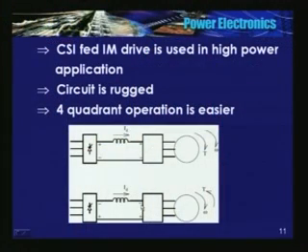Now we want to go to the second quadrant or fourth, depends on which one you have taken, T along x axis or y axis, it does not matter. So what do I need to do? I have to interchange the polarities here by increasing alpha above 90. Of course, current direction is the same. You cannot reverse the direction of current.